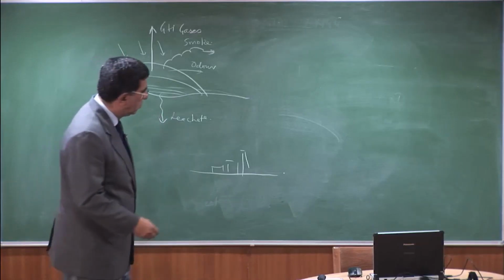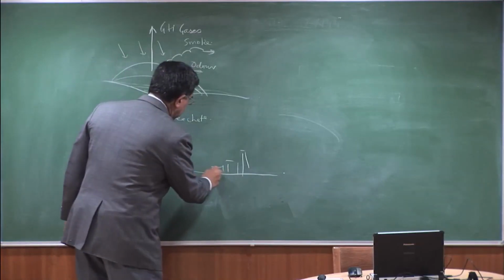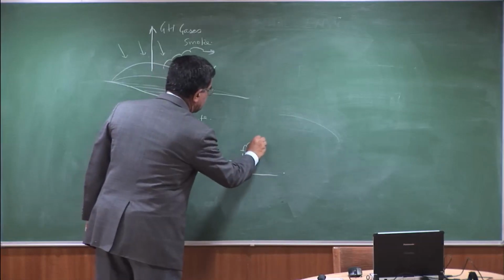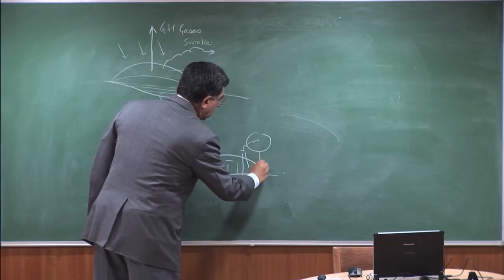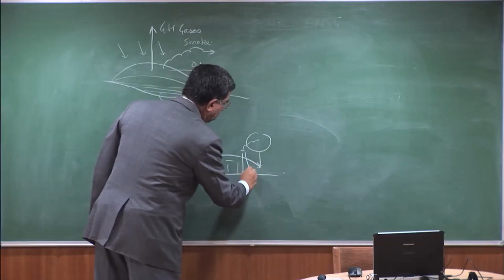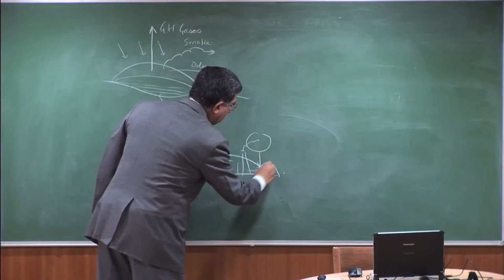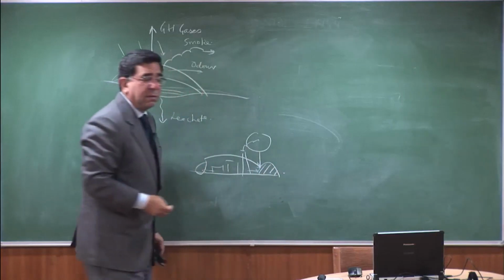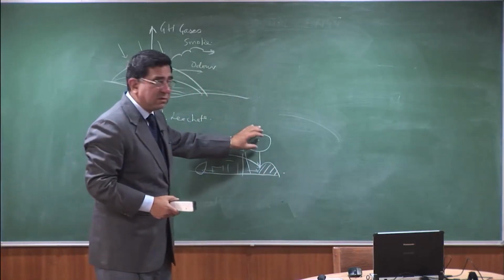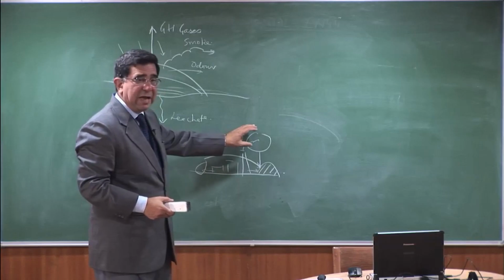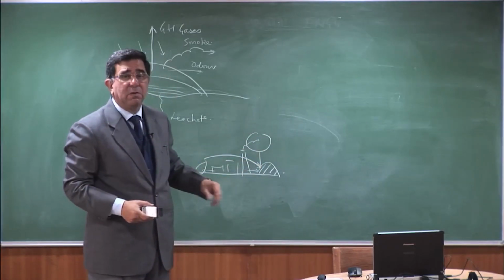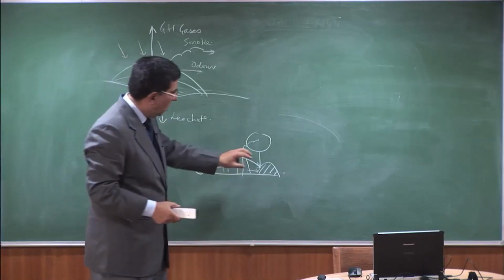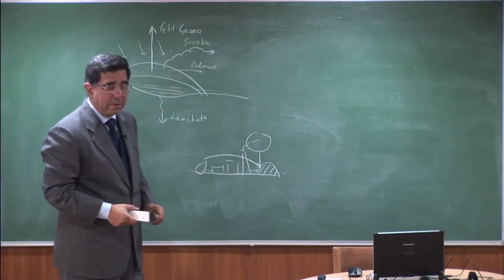And as I have already told you, the more I restrain the liquid waste and the gaseous waste, the more both of it comes to the ground along with the solid waste which is coming out, because gaseous waste will catch the ash and bring it to the ground, liquid waste will go to an effluent treatment plant and it will give the sludge, all of them becomes solid waste.